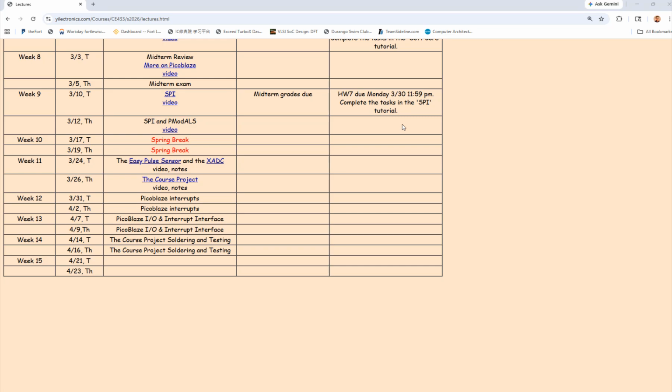ASIC stands for application specific ICs, right? It could be just a digital ASIC. It could be an ADC and digital and then communication protocol ASIC. So our ASIC actually does pretty much everything except the amplification, because FPGAs don't have analog circuits and they don't have op-amps in them, but they do have ADC. So everything after the ADC, including the ADC itself, will be on the ASIC.